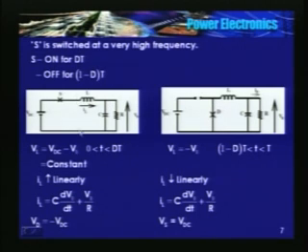So the voltage across the inductor is VDC minus V naught till the switch is on, which is constant. Therefore di by dt is constant, which implies that IL increases linearly. What is the KCL at this point?